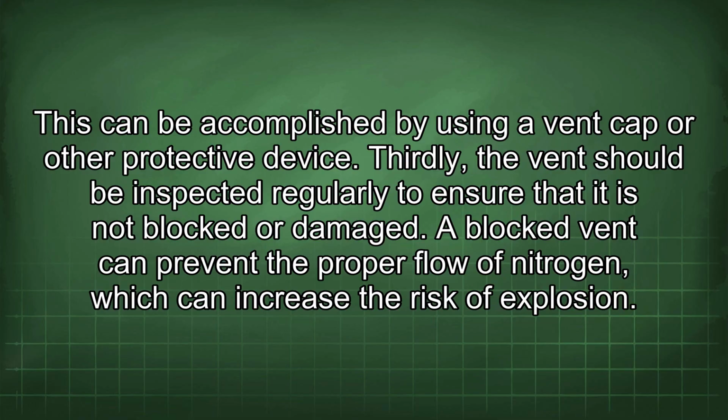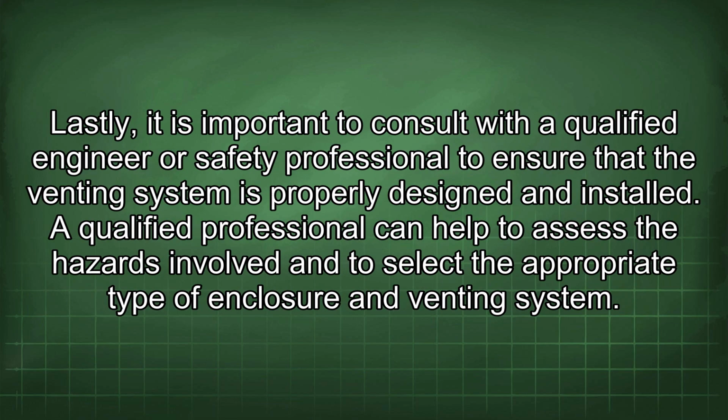Thirdly, the vent should be inspected regularly to ensure that it is not blocked or damaged. A blocked vent can prevent the proper flow of nitrogen, which can increase the risk of explosion. Lastly, it is important to consult with a qualified engineer or safety professional to ensure that the venting system is properly designed and installed. A qualified professional can help to assess the hazards involved and to select the appropriate type of enclosure and venting system.